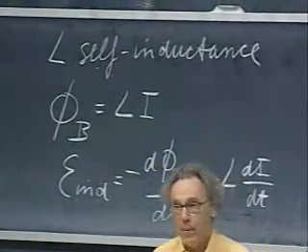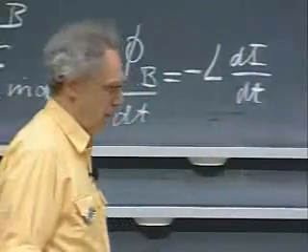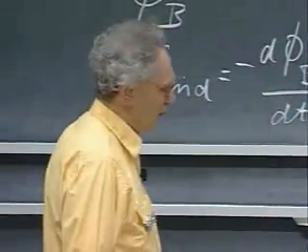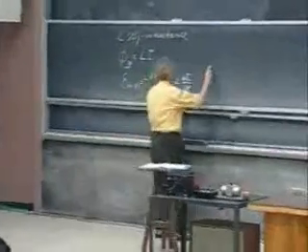L is only a matter of geometry. L is not a function of the current itself. I will calculate for you a very simple case of the self-inductance of a solenoid.